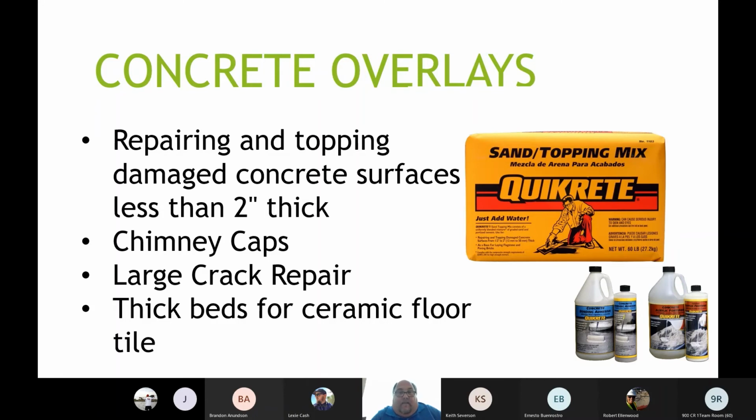Give yourself about a 1/2 inch, because that's usually about what that product's for, like a 1/2 inch wide, 1/4 inch deep. So you want to stuff the backer rod down in there on the more severe cracks, because you just need to seal them. You don't need to fill it, because I've actually poured bags and bags of self-leveling down a crack thinking it would just fill real quick. Well, it had to fill a void underneath it that was washed out.